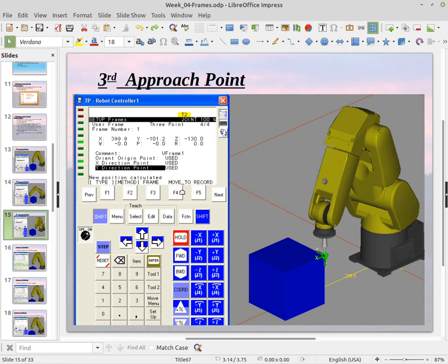And then also keep your finger near that hold key. All right, remember the hold key here. Anytime you're doing a move to, if you press the hold, it will stop the robot in a nice, smooth, controlled manner. Of course, if it's an emergency, you can always release the dead man. But that is harder on the robot because it's actually slamming on the brakes. So it's a nicer thing if you need to press the hold button.